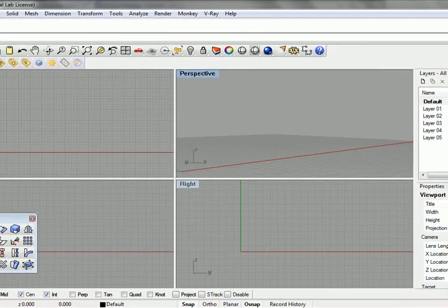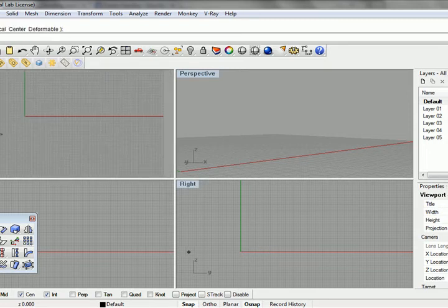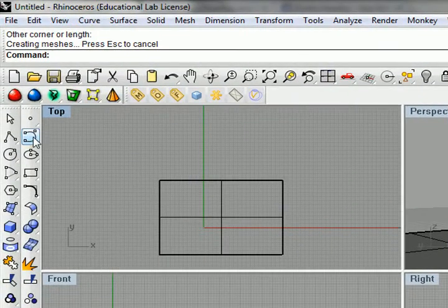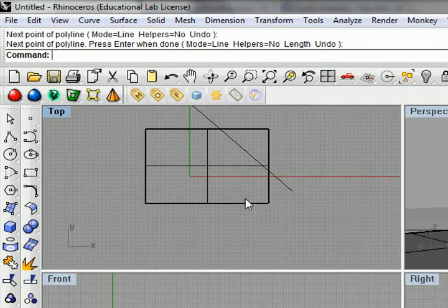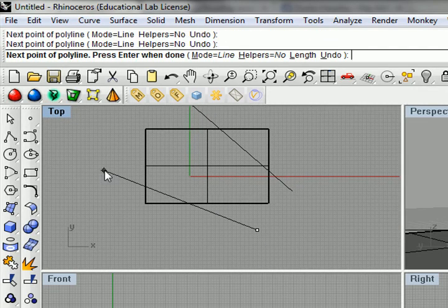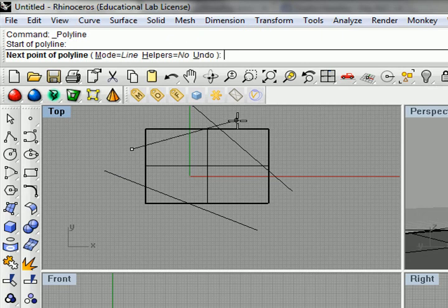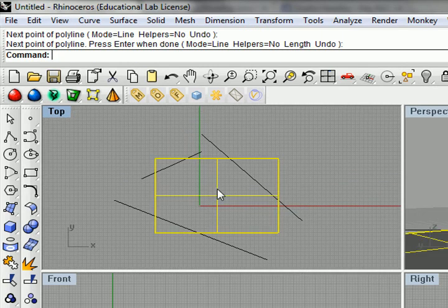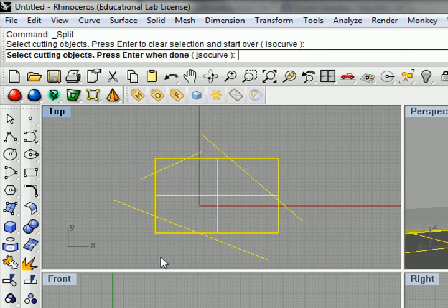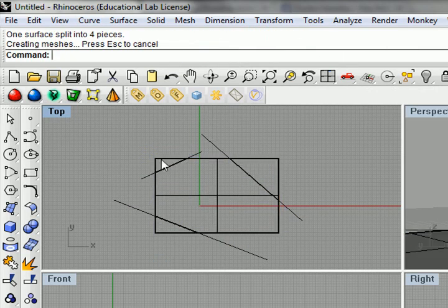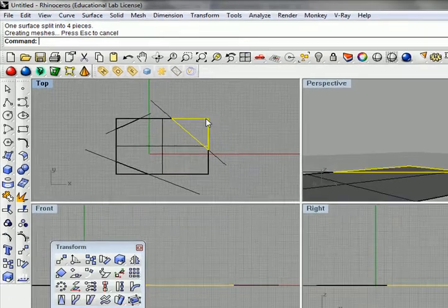If you have something where you're going to be folding geometries, I'm going to start in here with a plane. What you want to do is create some kind of a surface, and then create incisions using curves or some other bisector to trim that out. So what we can do is take this, use the split command, and select our cutting objects. And then we get a set of these guys that are set up here.